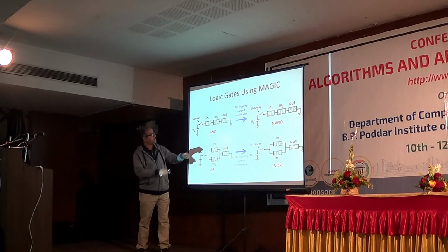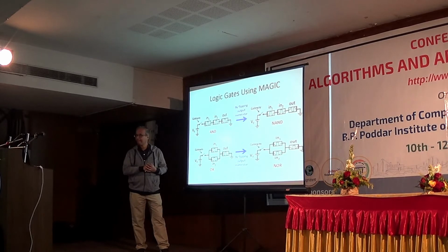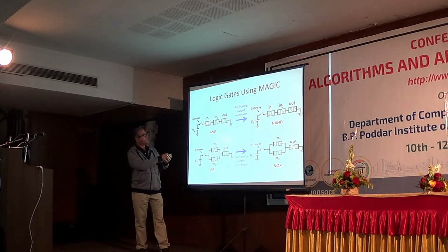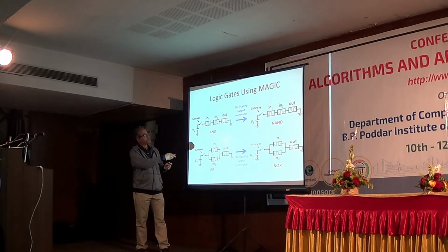So in AND, I connect the three memristors like this. All the solid ends on one side. Okay? These are the two inputs. So I initialize the inputs in a suitable way. And this is the output which is initialized to 0. I said for AND, initialized to 0. Then for gate evaluation, I apply some operating voltage V0 in the input.